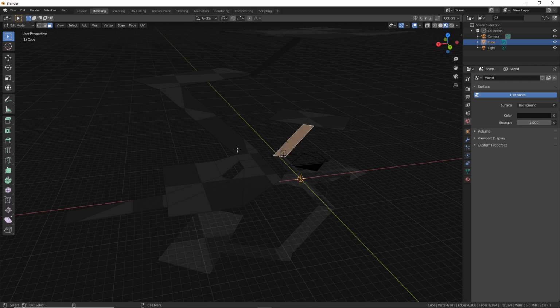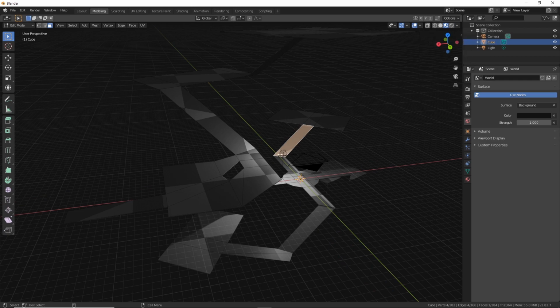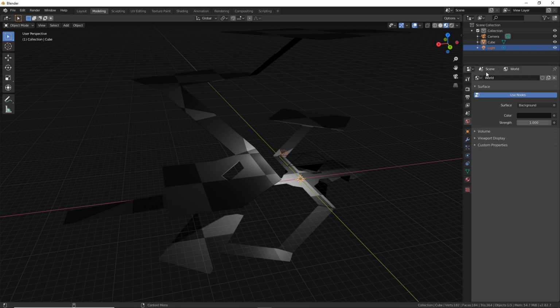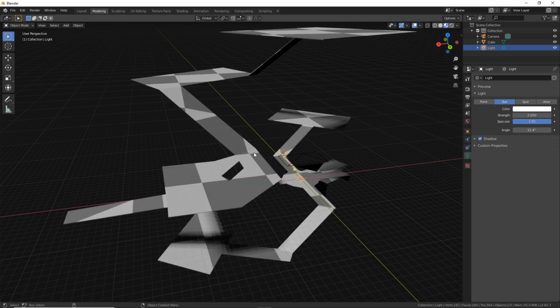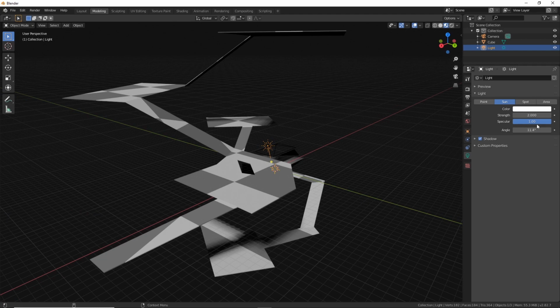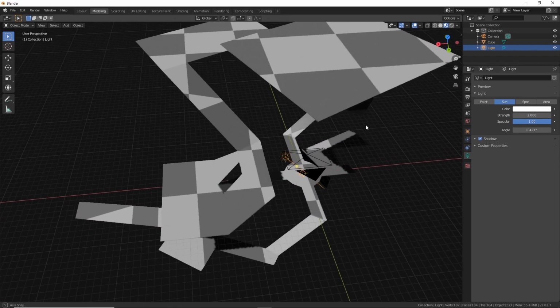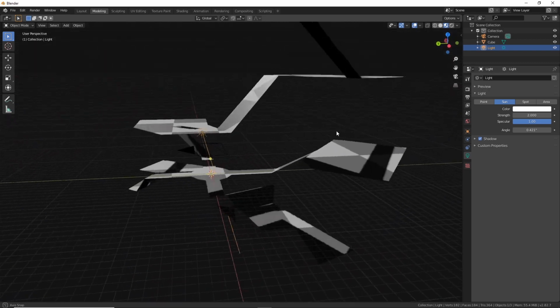Let me turn on the lights. Let's make it a world light. Turn on scene lights. And we'll make it a directional light. I'm in edit mode. Or a sunlight, I mean. Make it to brightness. And it's casting shadows, but I want it to cast soft shadows, so let's turn the angle down, just to create some more edges. It's kind of interesting.